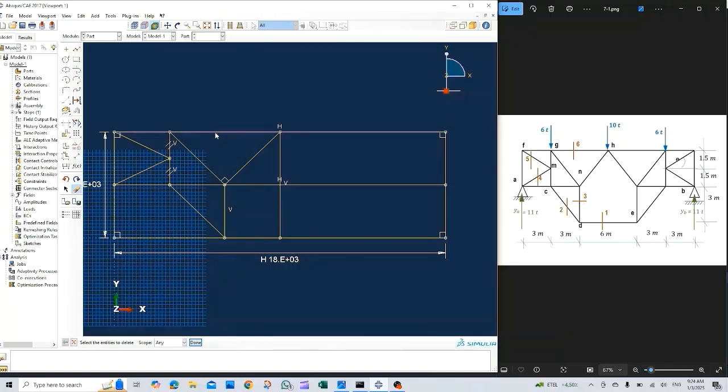See here, when you click on GH, the whole top chord is selected and therefore it must be deleted and redrawn just to achieve separate members. Done. And the delete icon is activated. Choose this bottom chord and done.